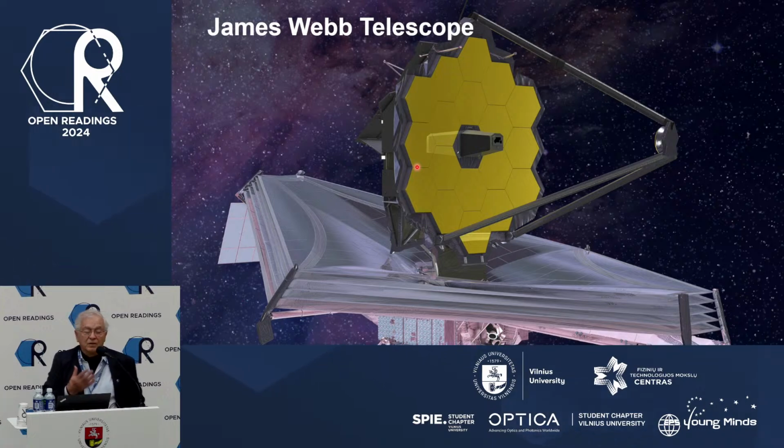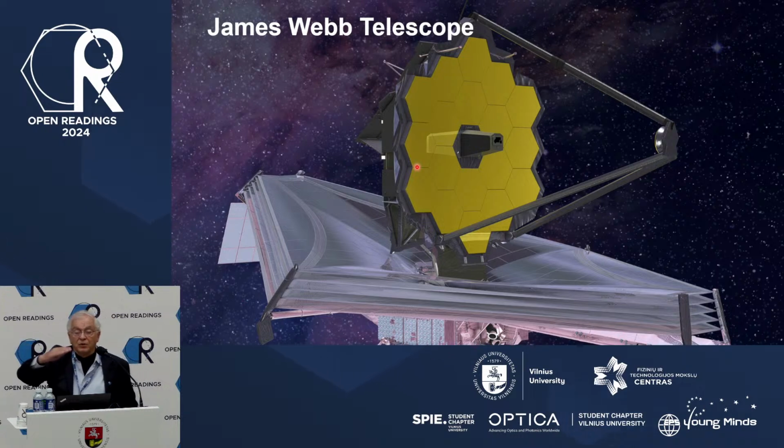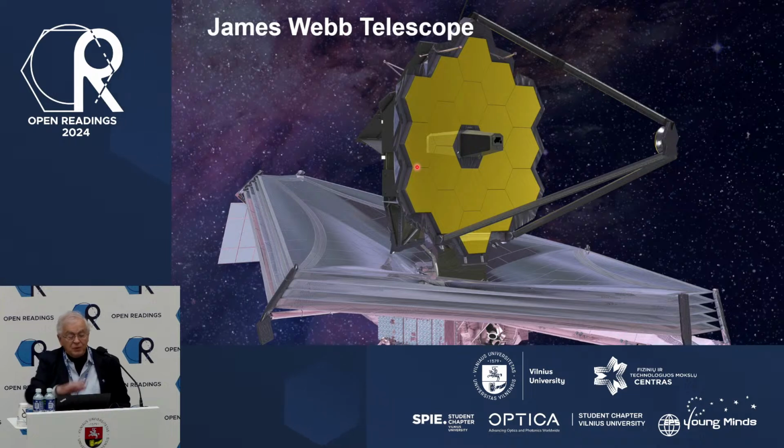And in addition, we wanted to make sure this telescope operated in the infrared at very, very low temperature, which is needed for the detector and for the telescope. So we needed the shade also to block all the heat coming from the sun. And that's partly why it is layered, as you see here. That helps reduce the thermal emission coming from the sun, so we can get down to a few degrees absolute. So these were some of the little challenges that the people developing this had to face.